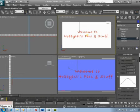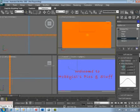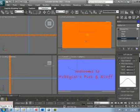Still in polygon selection mode, with the text polygons selected, let's open the soft selection area on the Modify tab and check Use Soft Selection. Here's where you start to notice that lag. Because after a couple of seconds, the entire front view shows as completely selected. The reason we've lost our text selection is because the default fall-off value is way too high.